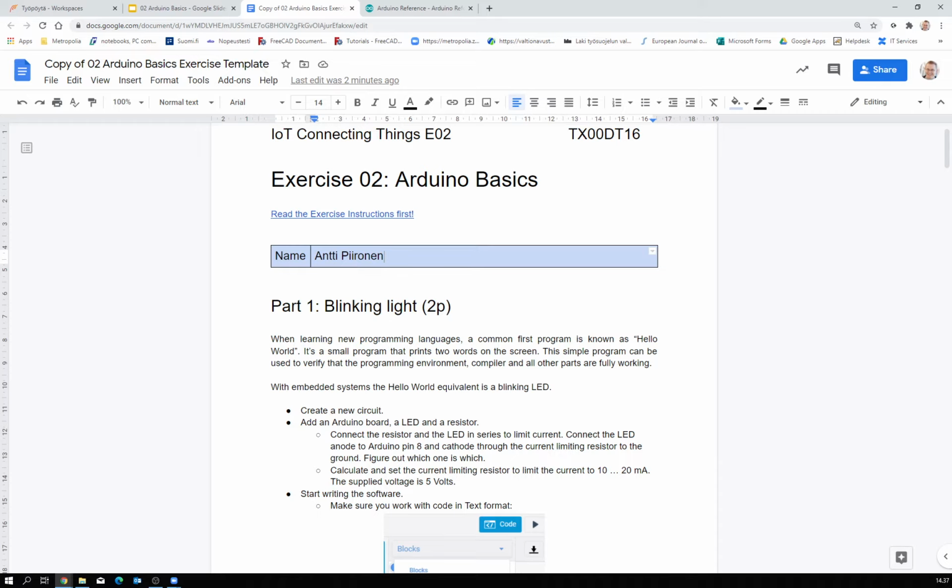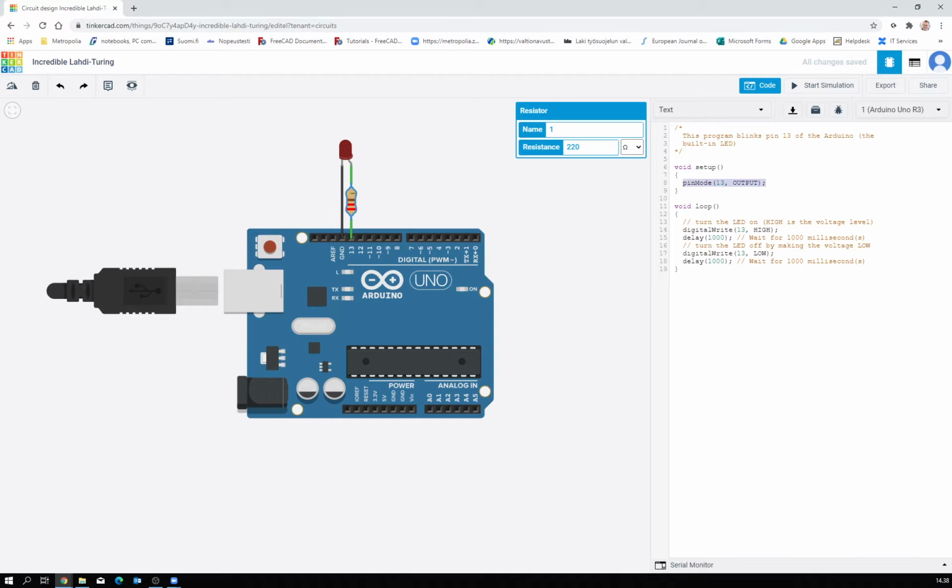You might have just a buzzer, you might have some electromechanical device there, you might have an LED there. So how to make sure that you have controlled the system? Well, blinking LED light. That was already in here, a blinking LED light. 1 second high, 1 second low. Current limiting resistor. I think that's just about right. This would work just fine for starters.